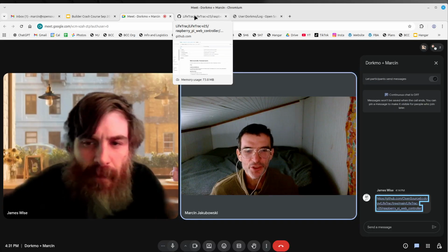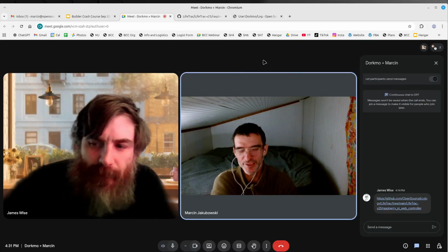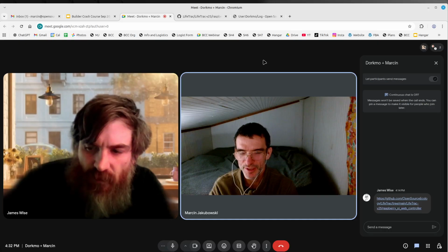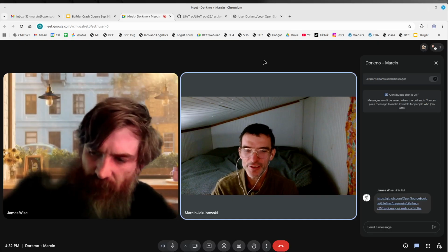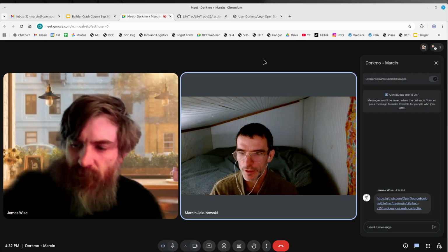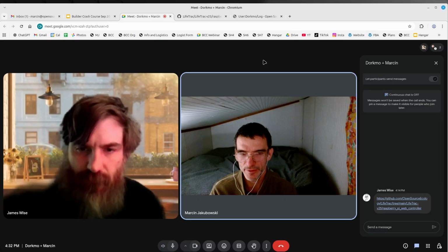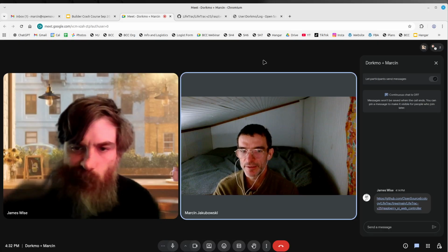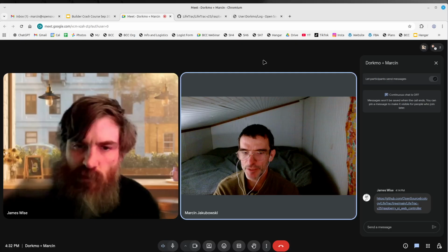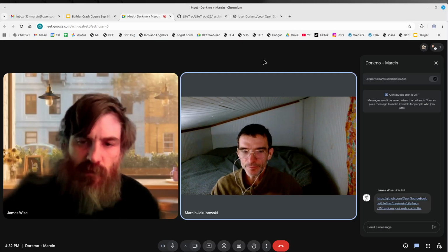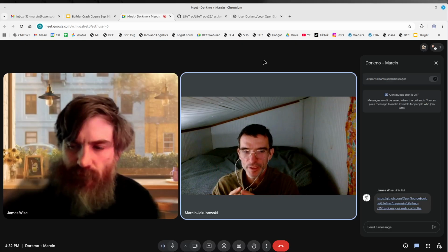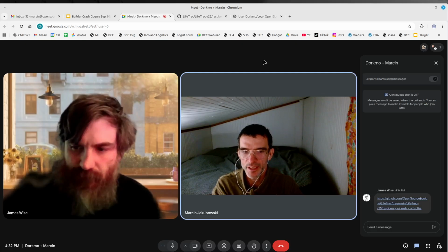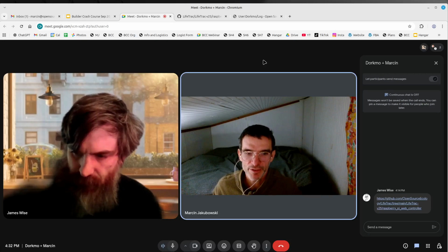So the absolute cheapest you could ever go is these cheapo 15 horsepower engines. Let's do a mother power cube that's got the reservoir, coolers, fans, battery, and to it connect as many of the engine slash pump units as you like. So you have the whole hydraulics in one mother power cube, and babies, which are just engine plus pump. And the part that goes out is the engine, right?